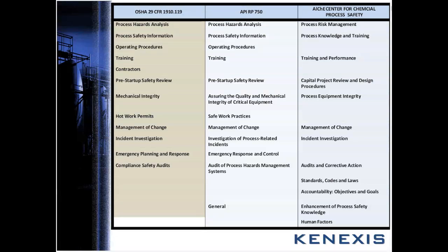And using this approach, the process design, the technology, operational maintenance activities, procedures, emergency preparedness plans and procedures, the training programs, all these elements work together, and it impacts the processes, and they're all considered as a whole. So process safety management is the proactive identification, evaluation, and mitigation to prevent chemical releases that could result from the failure of a process, a procedure, or equipment.